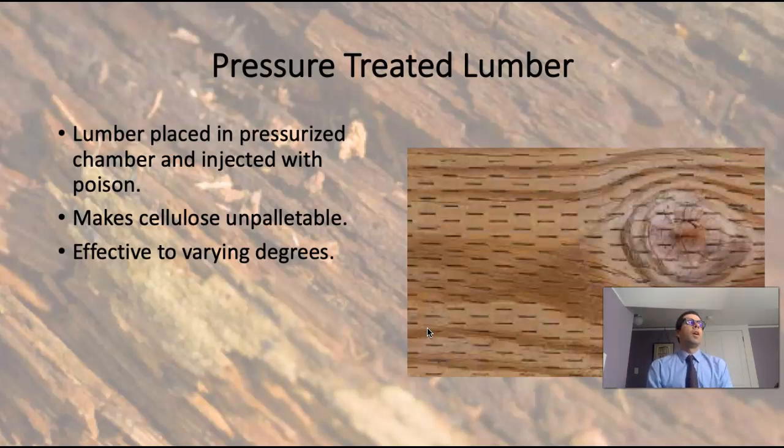Okay? That's kind of the weak point in this stuff. People don't realize that this treatment doesn't go all the way through. Okay, so when you cut pressure treated lumber, make sure you seal up the wood in some way.